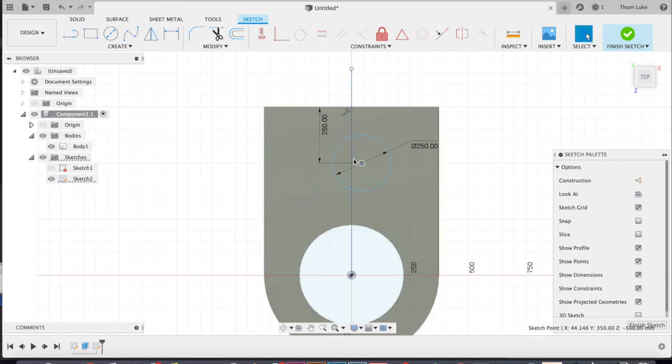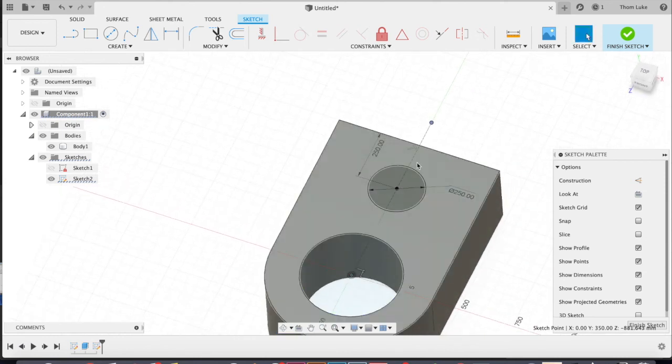What it now allows me to do is say, create a coincident. Now I've got a fully defined sketch, but this line won't be integrated into any sort of feature going beyond this. So you can draw lines which are essentially like using a pencil. You're essentially just using them for construction, not your final work.